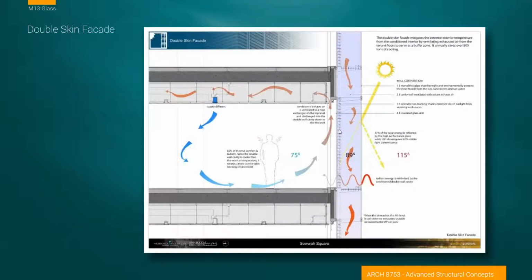They do offer advantages, but sometimes the advantages that we end up finding have nothing to do with the original intentions of us conceiving of the double facades. For instance, the double facade is to create some sort of extra barrier for a better thermal performance. And then typically what is being discussed nowadays is how this outside air pocket can become a way of stacking heat away from the building or creating ventilation schemes.